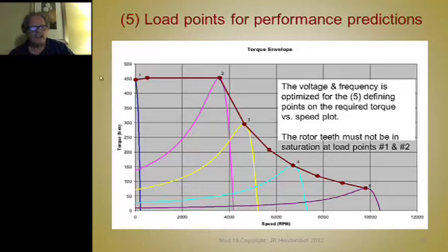You need to identify that one, and that's really the same as this one. If you optimize the magnetizing current and the torque producing current for these 5 points, you've identified this envelope, and you've shown that the drive you have and the motor you have designed, those together will give you this operating envelope. And that's the importance of the torque speed curve. In the application, this motor will operate anywhere within that envelope.